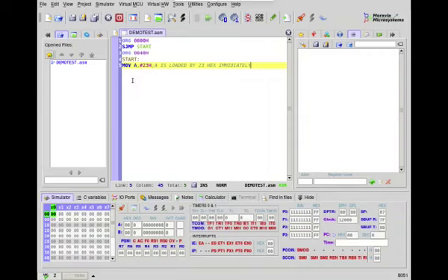So here in microcontroller there are no instructions such as MVI in 8085. Here all instructions are just mov. So if I am writing mov A, #23h, the meaning is A is immediately loaded with 23 hexadecimal.